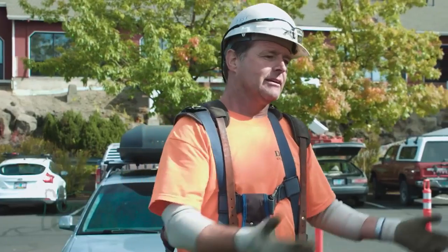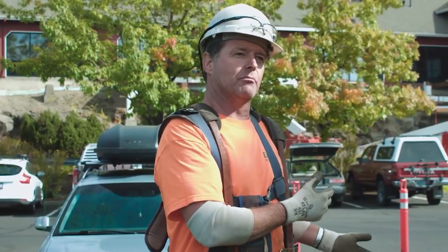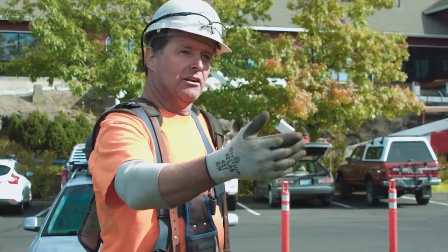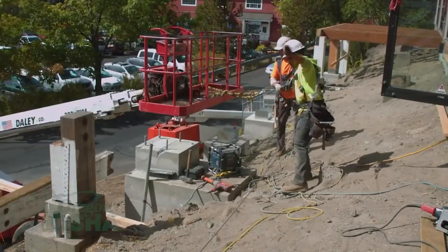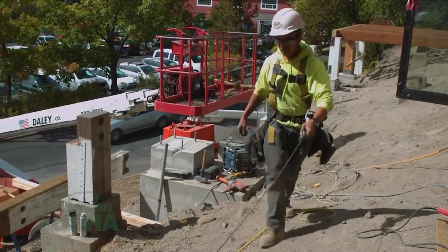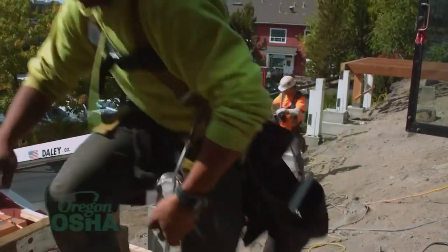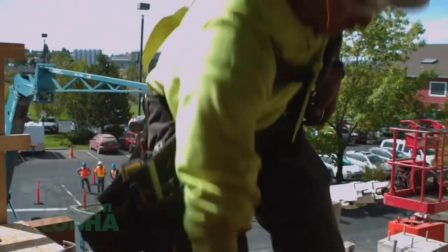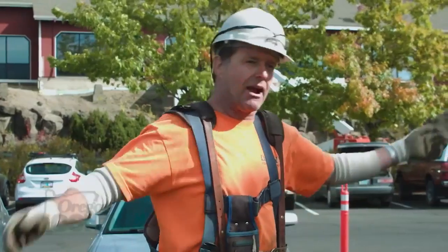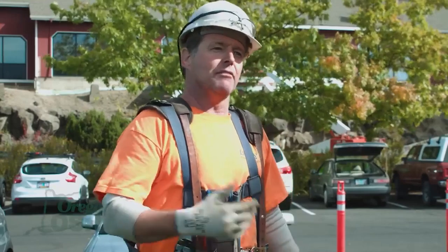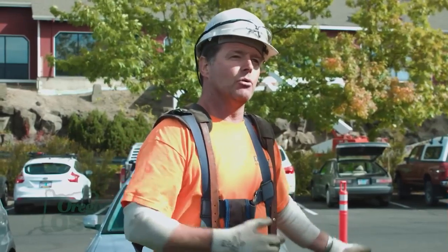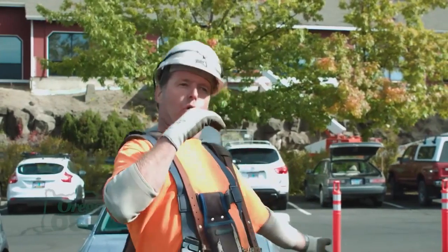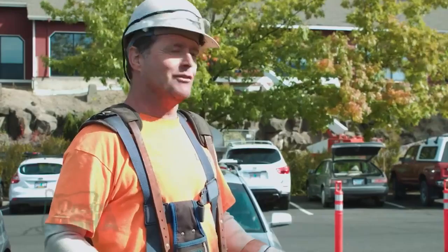Well, that taught me that it's well worth the extra $1,000 to buy a retractable, because as you're walking, it always sucks the slack up. There's always tension, and you can't trip on your safety gear. Whereas with the cheaper ropes, you must manually adjust the length, and that's in theory, but in reality, most guys don't, and they drag around a surplus of rope. Invariably, like I discovered that day, you end up not seeing the rope when it's behind you on a roof and it's uphill, and when you step on it, it rolls by virtue of just physics, and then you fall.